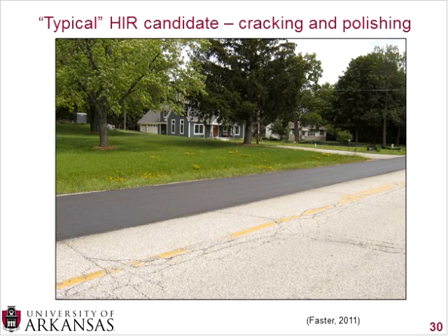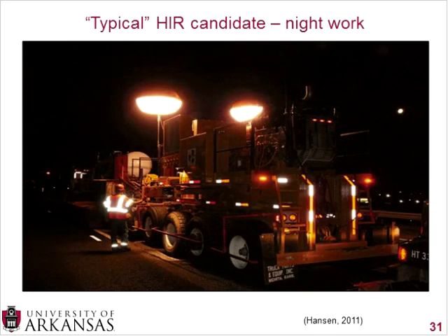So if you have a thick enough overlay on top of Portland cement concrete, you can use HIR to address some of these lighter cracking issues and the oxidation issues. Now, you do have to be careful, because if these cracks propagated through hot mix asphalt from the overlay, chances are the cracks will eventually propagate up through HIR. But this is just another solution to milling and filling, or just putting on some sort of thin surface treatment.